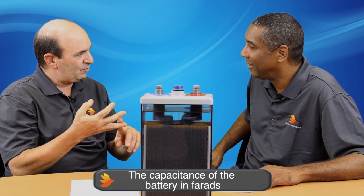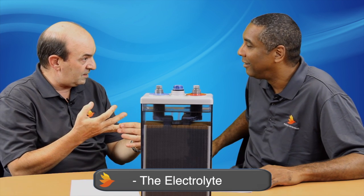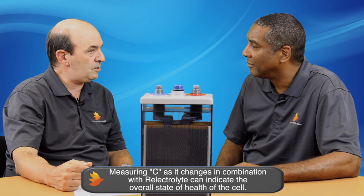Interesting. So that's the key word in the whole conversation. That's what you're measuring. That's one of the parameters that we're measuring. We're measuring the capacitance of the battery in farads. We're measuring the individual resistances, which include the electrolyte, the metal, and the leakage. C also changes as a battery ages, and measuring it in combination with our electrolyte, which is commonly expressed as impedance or admittance testing, can indicate the overall state of health of the cell.